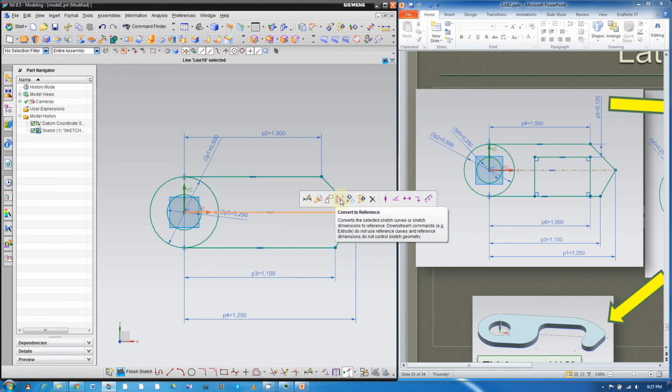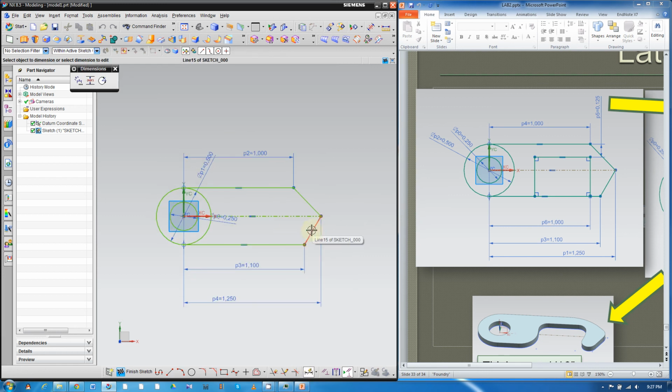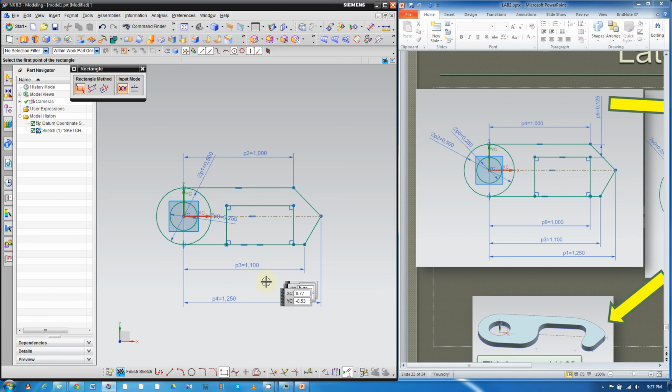All right, next is this rectangle. I think there's no dimension here. Well, it's just a random rectangle. Put the rectangle first, then give it some dimensions. So the spacing between this top and the rectangle is 1/8. So you can type in 1/8.